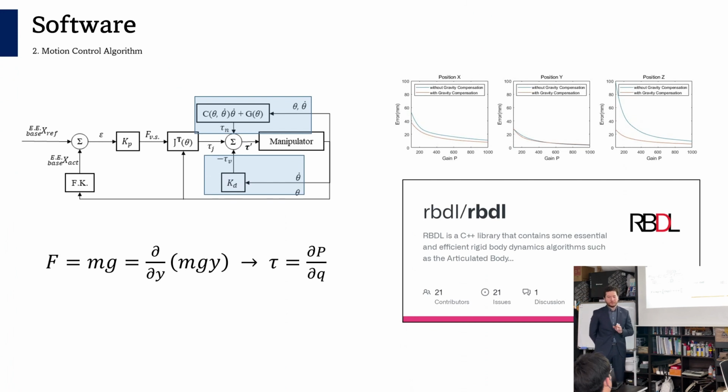Nonlinear effects compensation is necessary for improving accuracy with lower gains, reducing end effector pose error without compromising compliance. I utilized a rigid body dynamics library, which is a fast and accurate calculation method for easily getting the nonlinear effect torque for each joint.